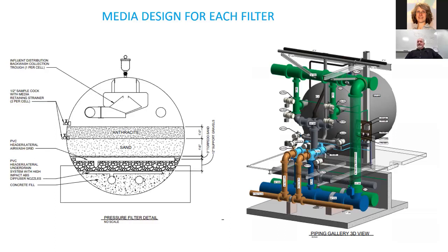There's a question about testing for PFAS. Yes, just last month a mandate was put in that every entry point to the distribution system shall be tested for PFAS. Currently we are on a yearly test. Any of the testing that we've done before has not shown any PFAS. All of the testing has come back non-detect.